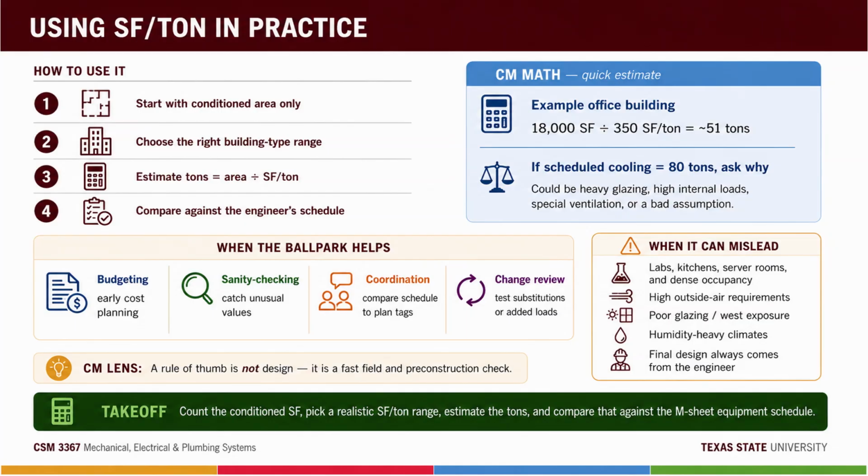The standard that governs how much is ASHRAE 62.1 for commercial buildings, and it sets minimum outdoor air rates based on occupancy and floor area. Think on the order of 15 to 20 CFM per person for typical office-type occupancies once you run the numbers. Quiz alert. ASHRAE 62.1 is the ventilation standard for commercial buildings. It sets the minimum outdoor air, in CFM, for occupant health. Ventilation is deliberate. Infiltration is leakage.